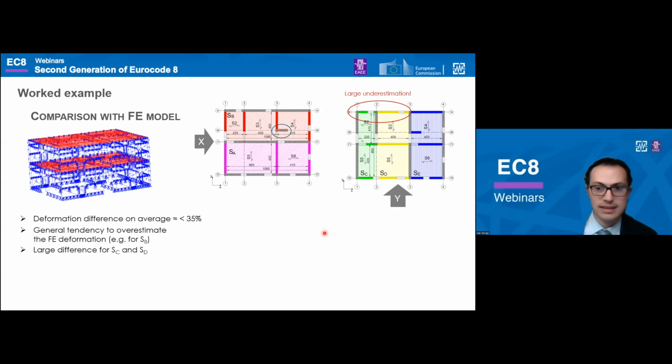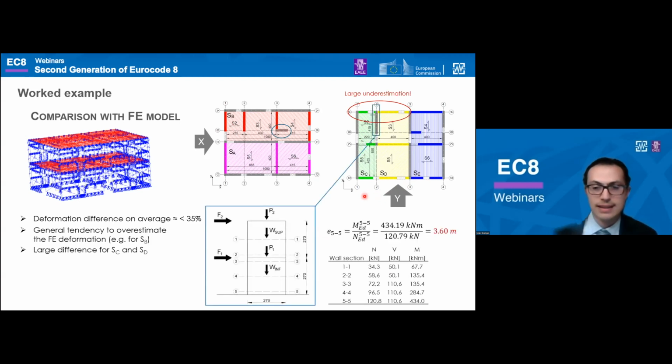And so, having seen that, the strength of wall line 2 was also checked against the shear force transferred to it by the two diaphragms. It's 50% of the inertial force related to the two diaphragms, and the calculated shear force exceeded the wall nominal capacity, in accordance with the model. Therefore, the diaphragm assessment procedure was performed again, but this time assuming an ineffective restraint at wall line 2.